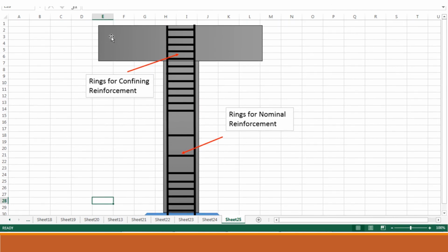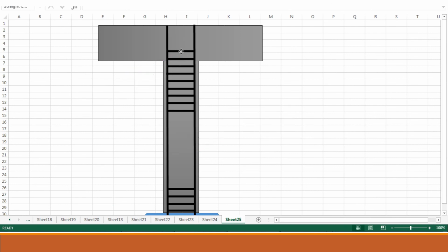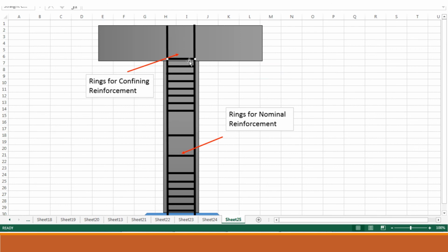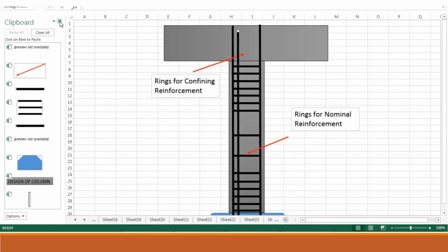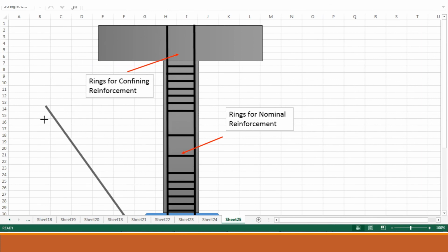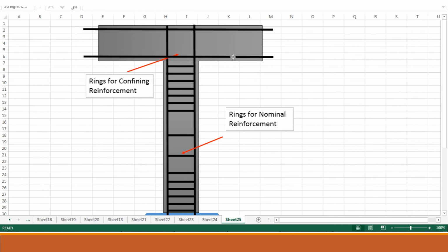And then there would be the beam reinforcement running parallelly. Now if the beam reinforcement is being provided in this zone, and if this is continuous, then there may be no need of providing the bars within this zone, and in that case we would have something like this, and the reinforcement being provided in such a way that this is the beam reinforcement that's running throughout, and then another beam reinforcement at the bottom.